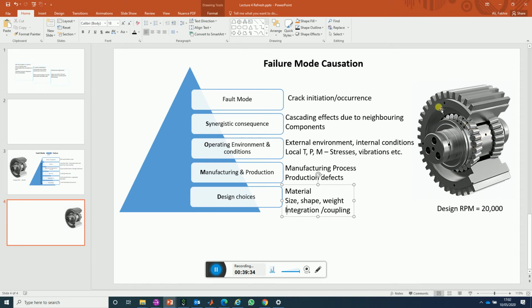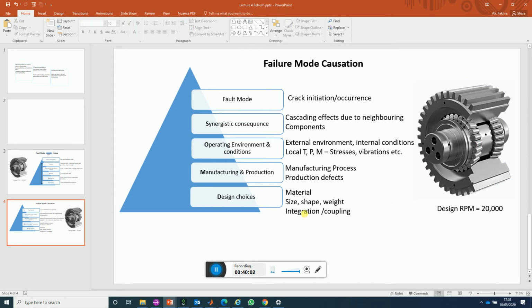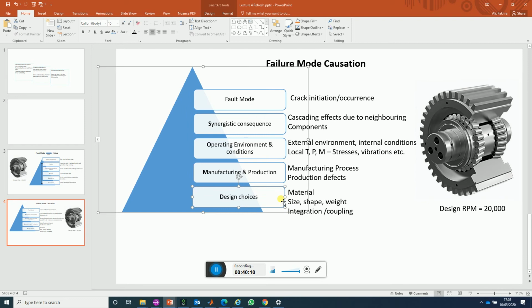Is the integrity of this coupling system appropriate for operating in such high frequency environments? Okay. So we really have to pay attention to how things are designed when we look at faults. It might be that this bearing is not even worth exploring or maintaining anymore because it's not designed well. They have used the wrong material to design it. So you're not going to put any effort in maintaining it. You're just going to say replace it, right?